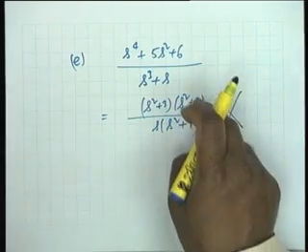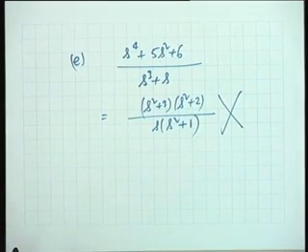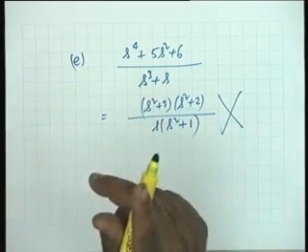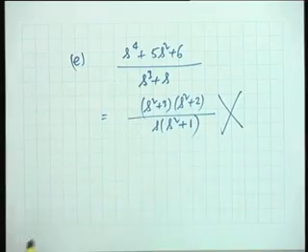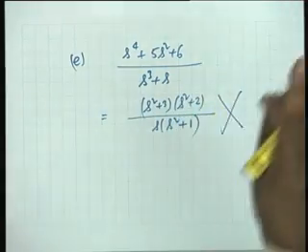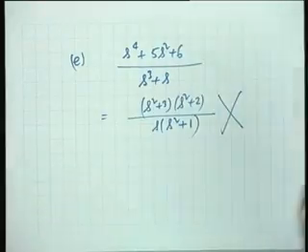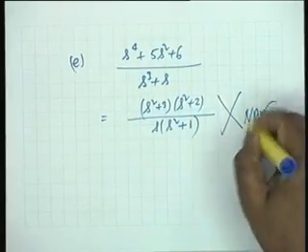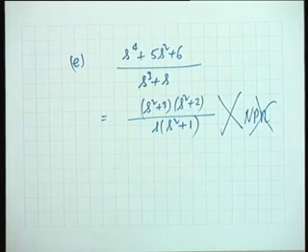If it is an odd rational function, and it's PR, it should be realizable as LC. It is an odd rational function, not realizable by LC, therefore it is not PR. It is a non-PR. Is the argument clear? Logic clear? All odd rational functions which are PR can be realized by LC. Alright. If it cannot be realized by LC, it cannot be PR.